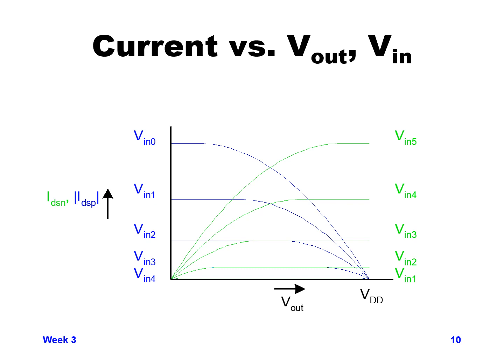The blue curve would be how much current would be going through a PMOS device depending on the gate voltage and the output or drain voltage. And the green curve is the amount of current going through an NMOS device depending on its gate voltage and its drain to source voltage.